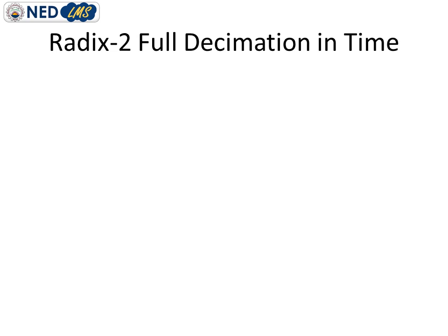Or if you are considering k as 3, then 2 raised to power 3 is 2 2s are 4, 4 2s are 8, then n is equal to 8. So it means your original signal must have 8 number of sample values. But again, the sample signal does not always appear in this fashion. It may have some sample values such as 5, which we cannot represent as the power of 2.